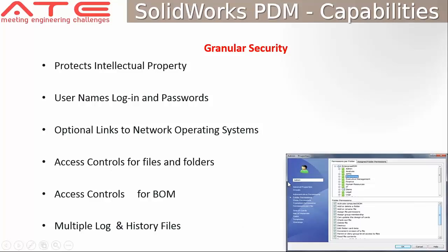So what is granular security? SolidWorks PDM requires a user ID and password to log in or to access any data, so that it can protect the intellectual property. Operational links to network operating systems let you control the access for the files, the folders, and the bill of materials, and you can also maintain history and multiple log files. It can manage the data in a secure way, with multiple options like assigning folder permissions, file permissions, location permissions, as well as workflow permissions.